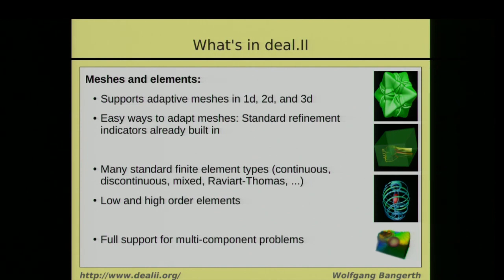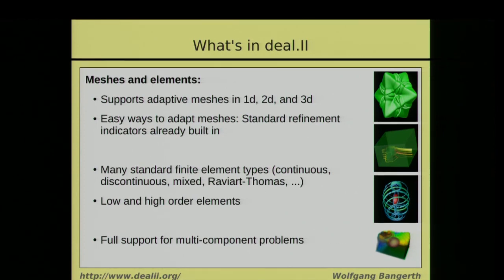One of the things you will realize is that even in 2013, when we taped these classes here, 3D computations are always expensive. And if you can do, let's say, the software development, or maybe even the solution of the real problem that you want to do in 2D, for example, by exploiting some rotational symmetry, maybe your problem really is two-dimensional, then you will find that it's a lot easier and a lot cheaper to do this, a lot faster too.